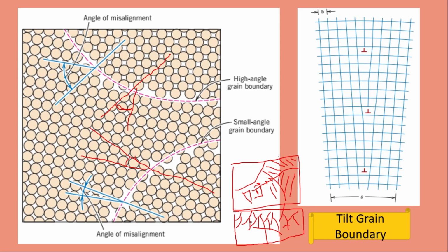So that's why those materials which have fine grains, which have a small grain structure, tend to be of higher strength compared to the material which has the large grain or the coarse grain structure. So the iron with a small grain structure would have higher strength compared to the iron with the large grain structure. I hope it's clear now.